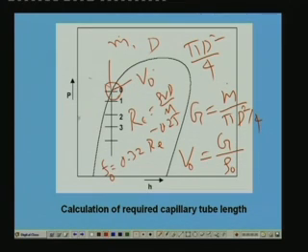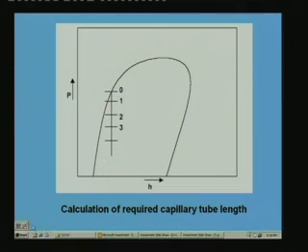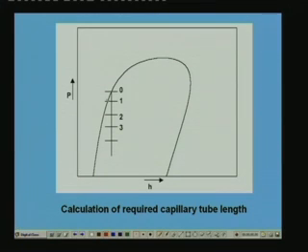Okay, then what I do is I assume suitable temperature drop, as I have already explained to you. Once you assume the suitable temperature drop, that means you come to the point 1. Okay, so you come to the point 1, and if you assume that the process is isenthalpic, that means H0 is H1, which is known. Okay, and this temperature is known because you are assuming a suitable temperature drop. So this temperature is known, so you can fix this state.